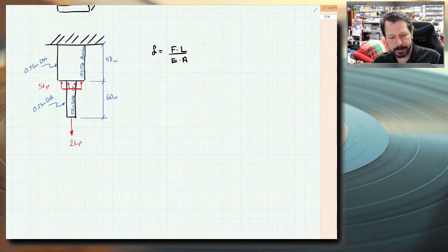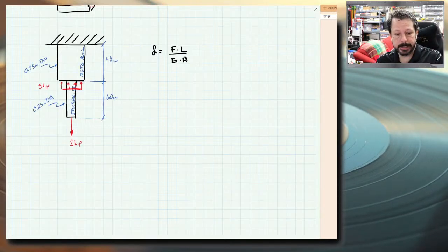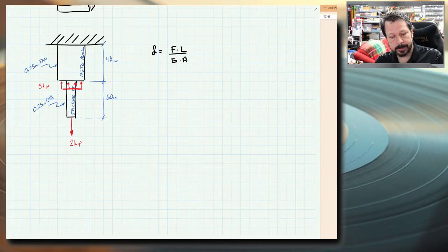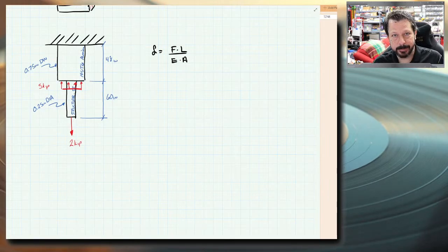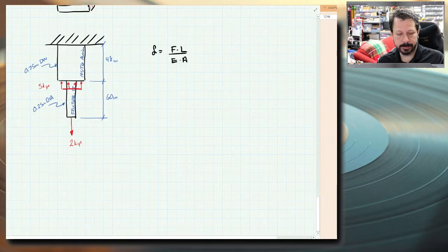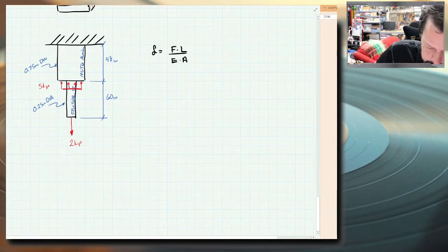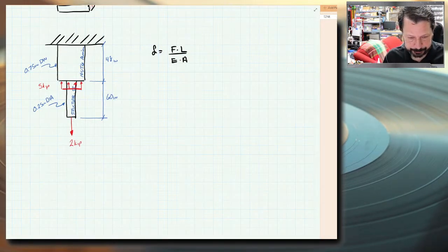One region that is the structural steel rod, because it will have the same force, the same material, structural steel, and the same cross-sectional area, so that can be one region. And then the other region will be the aluminum piece, where it'll have a force that's constant in the aluminum piece. It'll have a constant modulus of elasticity because it's all aluminum. And it'll have a constant cross-section because it is drawn as a 0.75 inch diameter cylinder. So I have to do 2 different regions.